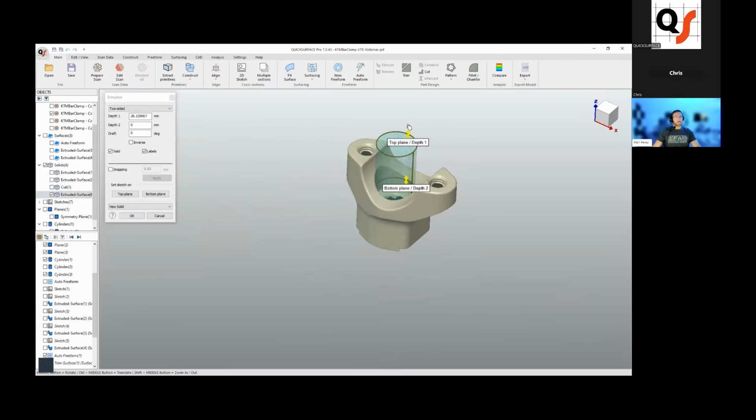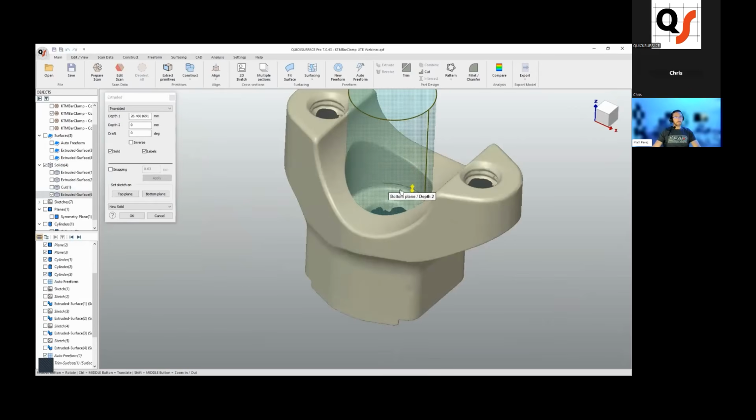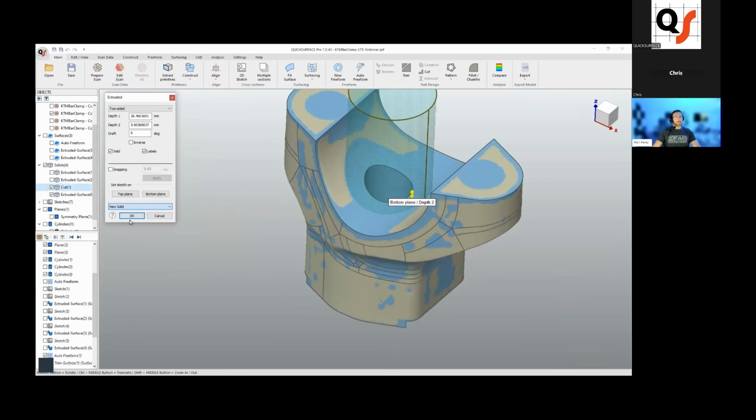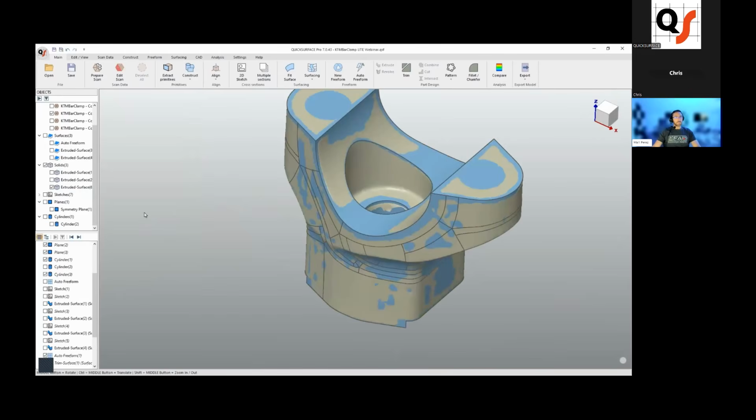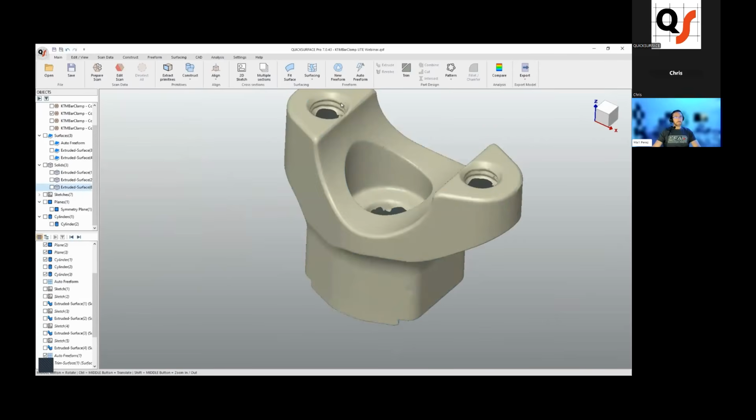I'm going to pull this all the way up through the solid body, pull it down, hold down Control to snap to that, bring back my solid, and use this as a cut tool. So once again, directly interacting with the mesh, giving us the ability to pull that data out. One more thing that we really need on this model is going to be these two holes here.